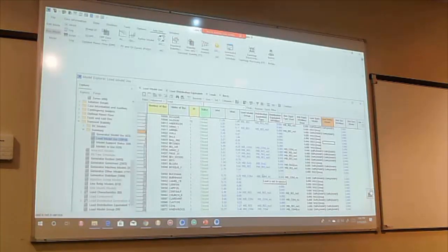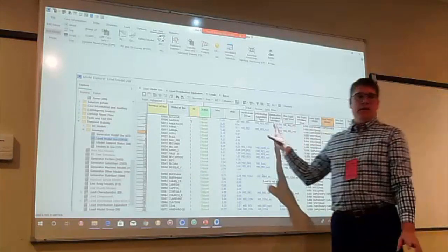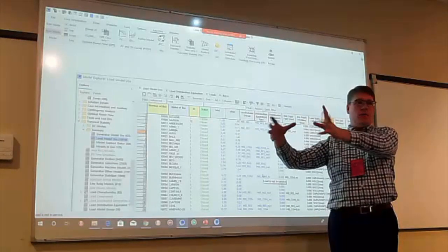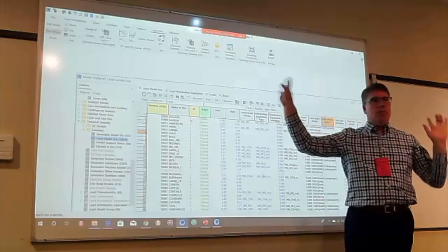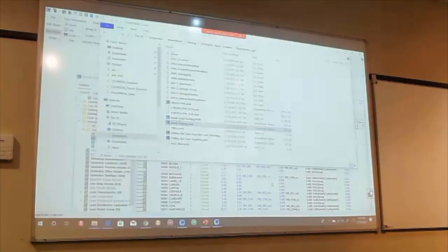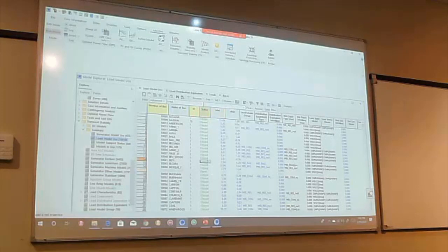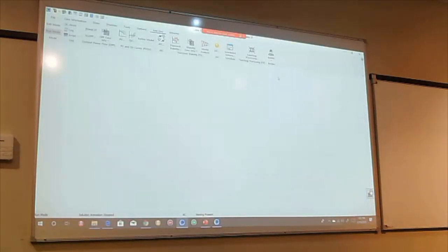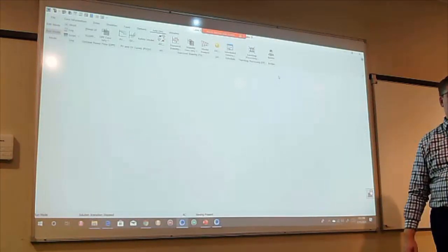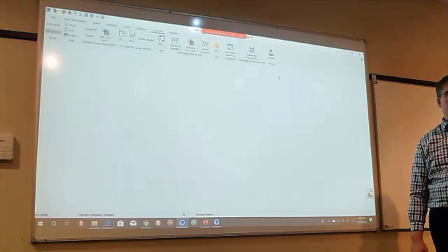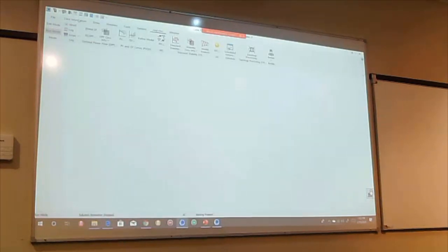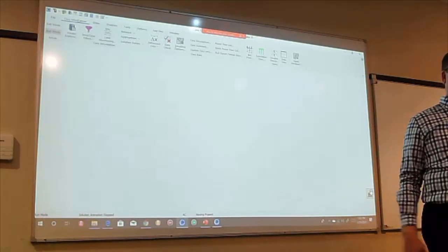And it permanently changed the power flow. Normally when you run transient, it doesn't do that. It makes a copy, messes with that, and when you're done running that stability run, it throws it away, and you start over and make a new one. Now with those, it still has constant power parameters? Correct. You can use this in the power flow environment with the constant power assumption. Yes. Go ahead, Eric. If you were to select all the loads and then right-click, it would do all of them.